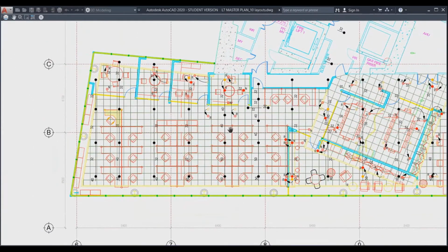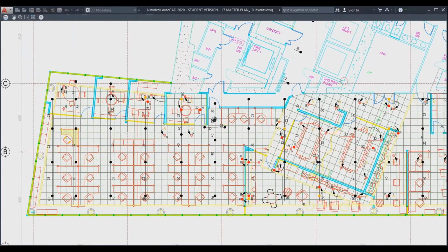But sometimes people want the drawing with the floor plan in gray color, I mean black color, and the remaining service drawing colorful, like red color or bright color or strong colors. At that time we have to use pen assignment to set that printing. Okay, so that's what we are going to learn today.